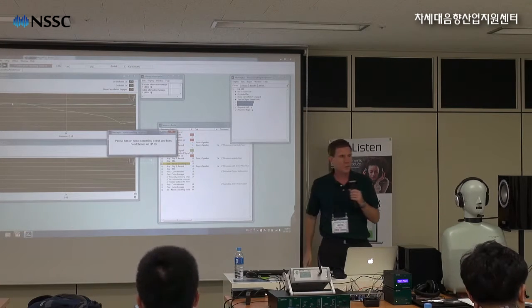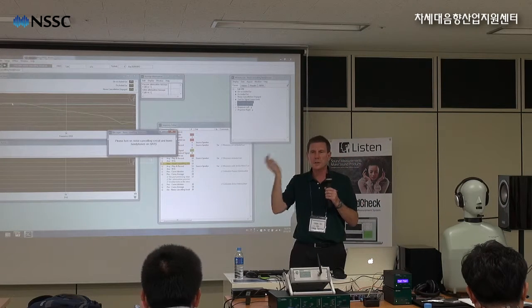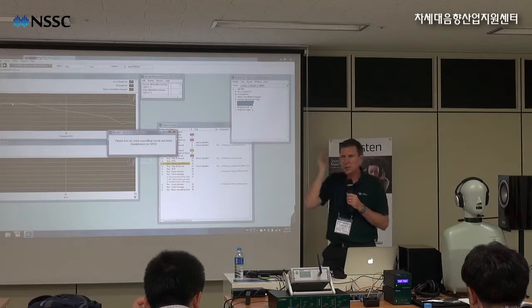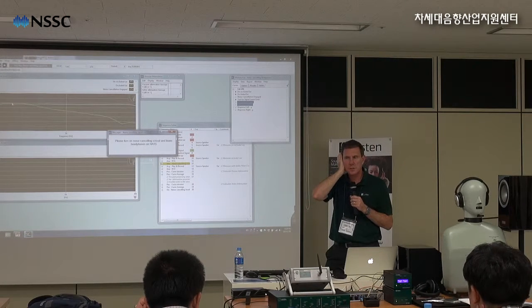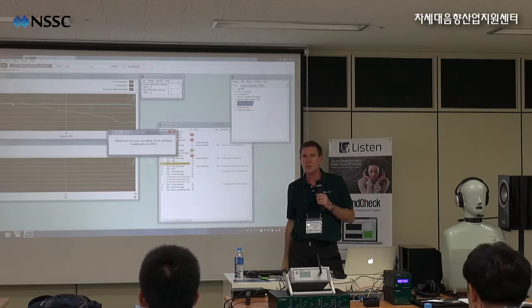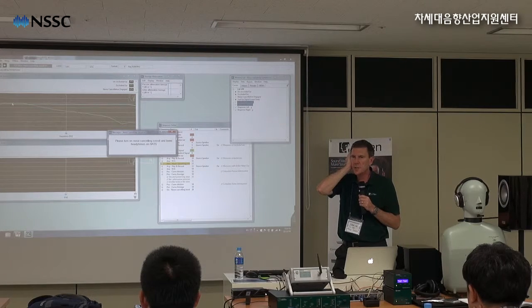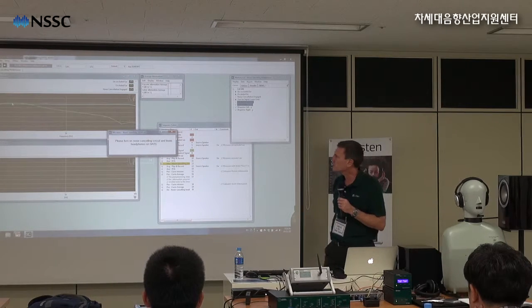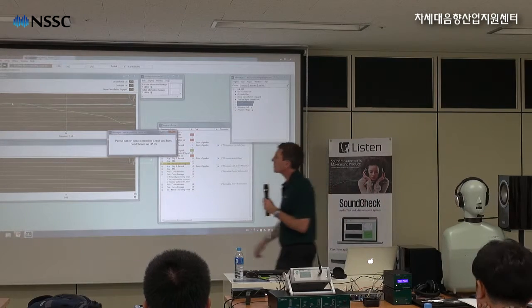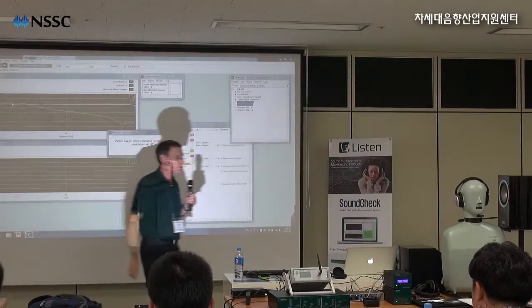Well, just think of this: if you cup your hand over your ear, you're actually creating kind of a resonance, which is going to cause an amplification at low frequencies. So just by the mere fact that the headphone is sealing my ear, I'm getting a resonance due to that cavity. So that's causing a little bit of gain here, but it's a dB or two, nothing significant.